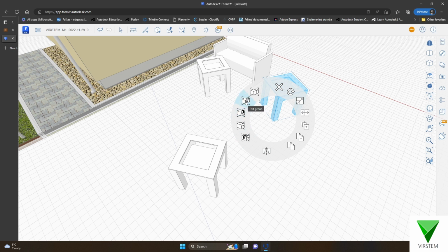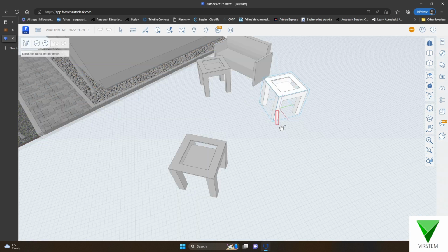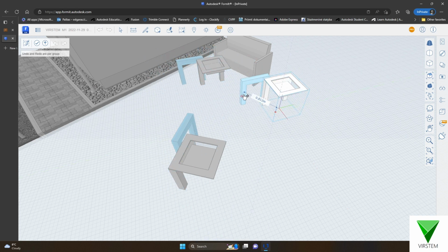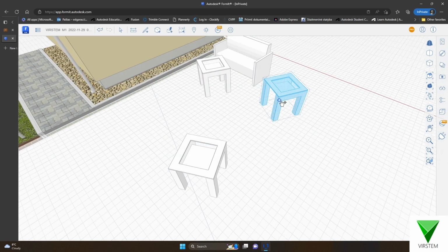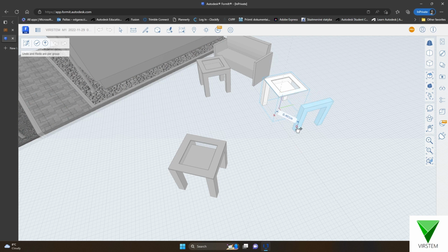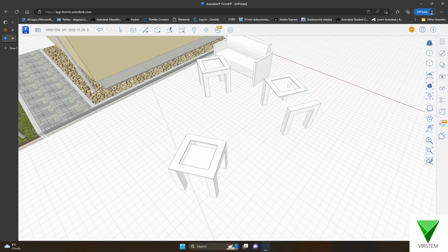So if I will edit object, you can see all other same group objects will change. So if I don't want that and I want to edit only this one, I need to make unique group, and in this case, if I change the position of this element, it changes only this unique group. If I ungroup, I have each element object separate, and I can modify these elements.